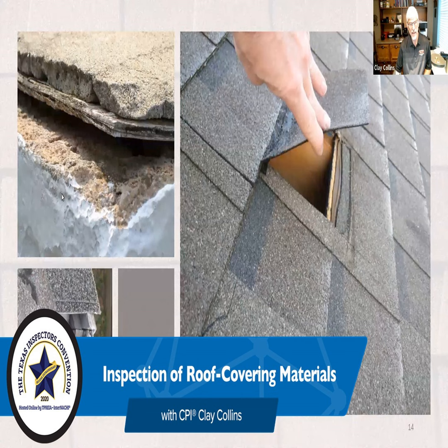So what about the underlayment? Well, this underlayment that you see there is very likely to cause those shingles to not lay flat. You can see all these places it's uneven. It's supposed to lay flat, but what we have very often is the roofer will just lay right over it. And then over here in the center, you see that we have there at the hip, they just cut it. You don't have the overlap at the ridge or the hip the way you're supposed to, or sometimes at the hip.